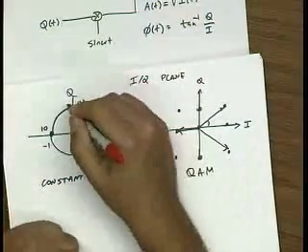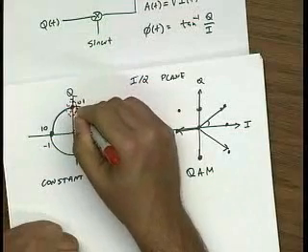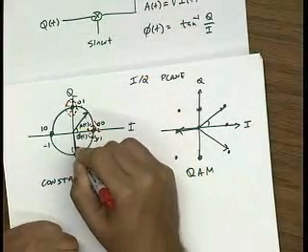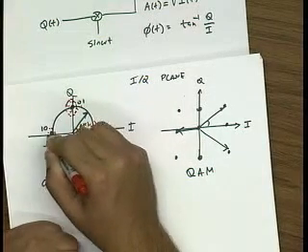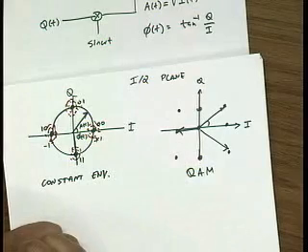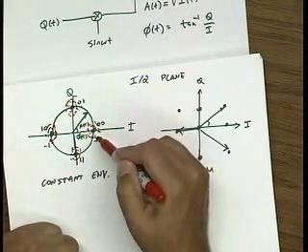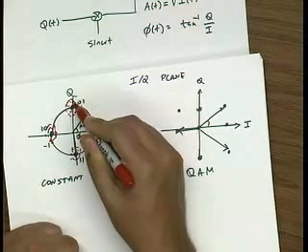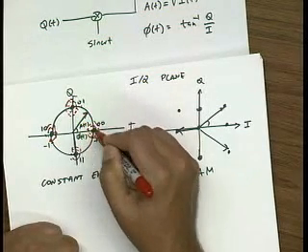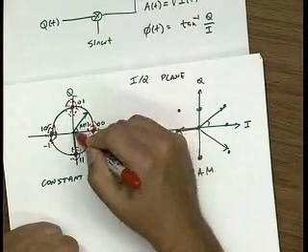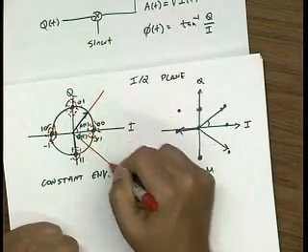So what you would actually receive, if you drew a bunch of bits that you received, they would generate, let's say, some scatter plots with clusters of points close to these original IQ points. And you can see that if you had to make a decision about if this bit were sent or if this bit were sent, you could be fairly confident that you're making the right decision, as long as, let's say, you're in this quadrant.